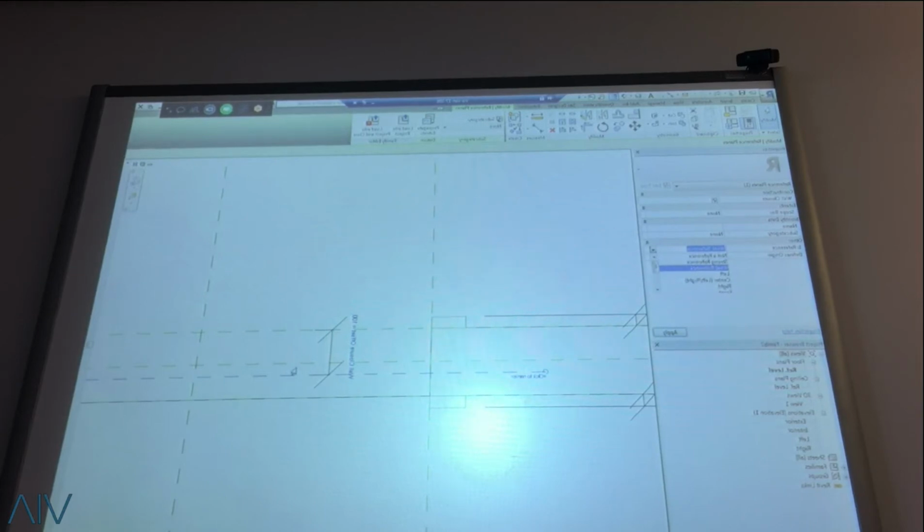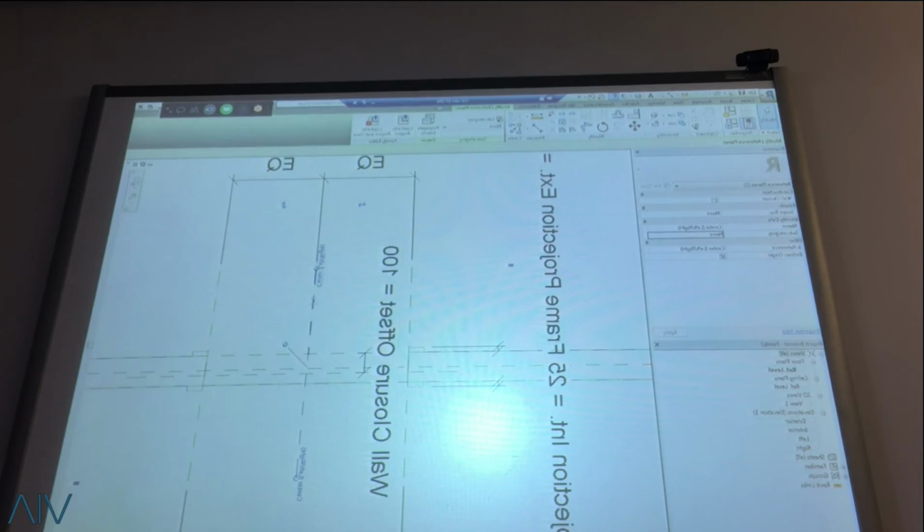So what this does is that whenever you align certain objects, this will determine which object is going to get picked first. If you say strong reference, that object will always get picked first. Whereas if you put not a reference, it means that it's not referencing anything. Keep in mind, there's also a subcategory as well. Right now I don't have anything, so that's okay. Now, define origin is something to be careful with. You see that right now when I select that object, it says that it's a defining origin.